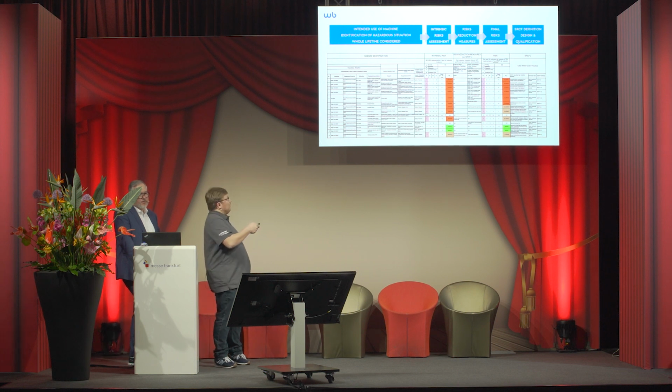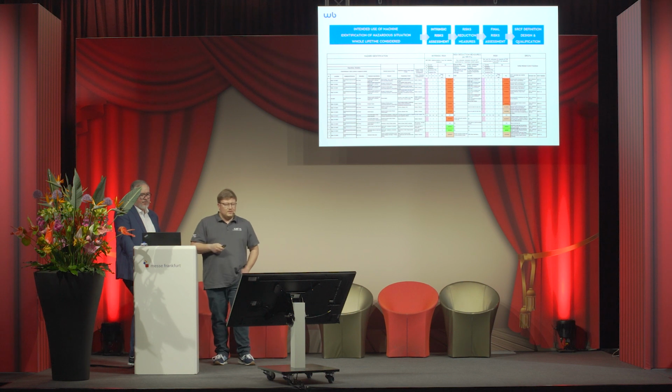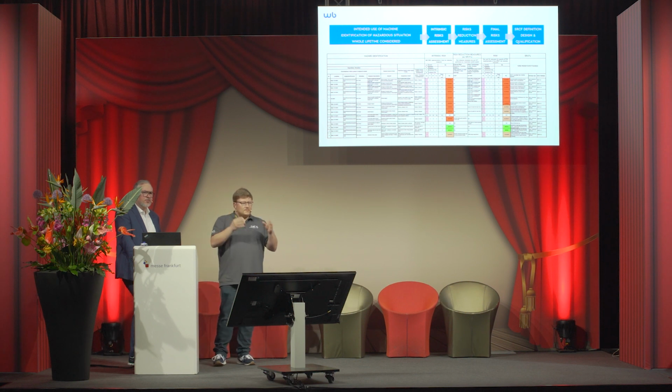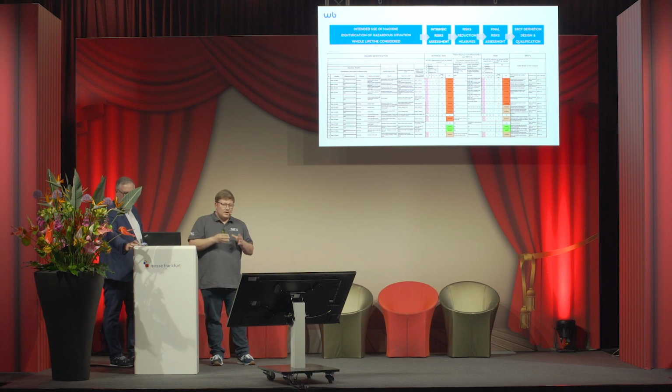Based on that, there is a second part, an intrinsic risk assessment. So basically we are saying, okay, in this case we've got this risk, that's this severity, there is this occurrence probability, this avoidance probability, depending on the scenario we've just identified. Based on that, we have to ask ourselves, is it possible to have some reduction of the risk?